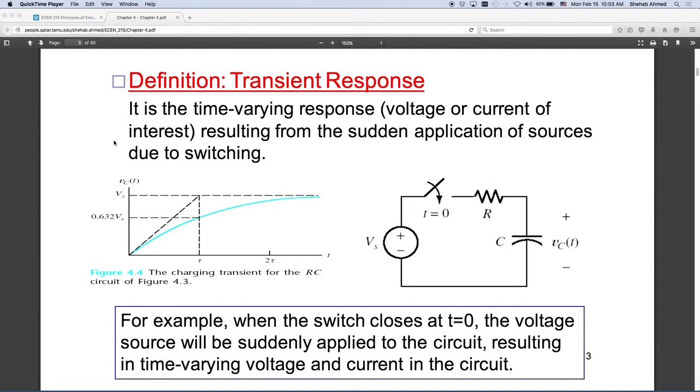The Education City trains will have these large capacitors on them. They come into the station and they charge the capacitors, so they need to stay at the station for a certain period of time. And then they can go from station to station, using the energy that's stored in the capacitance. The energy is half CV squared. By the time they reach the next stop, that energy would have dissipated to some extent. C is not going to change, so what changed? The voltage across the capacitance.